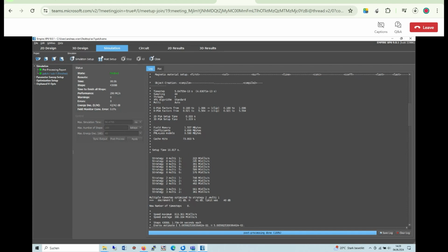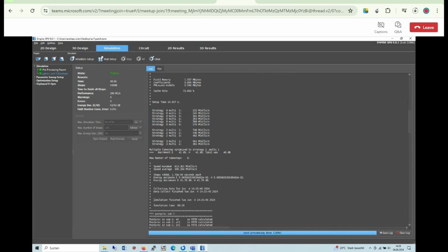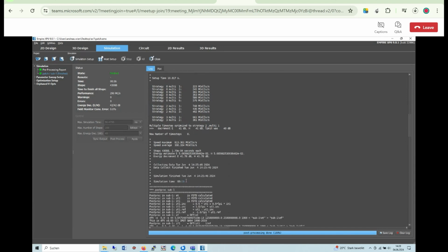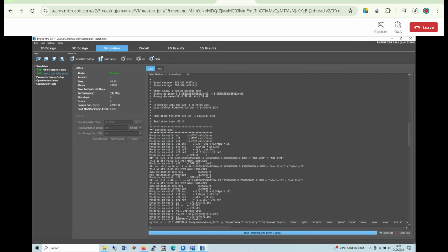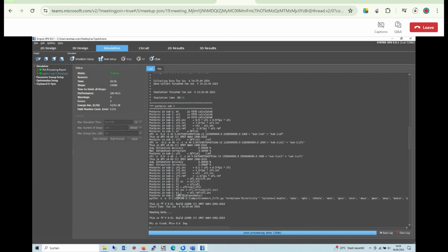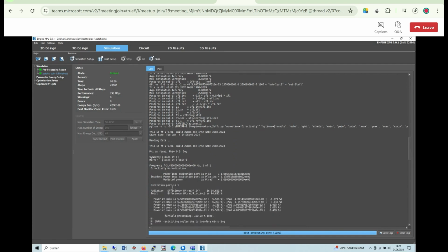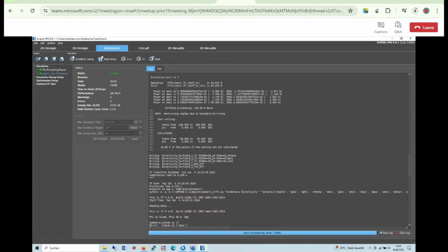And in the first steps, it tries to optimize the speed. So there's an automatic adjustment of the best strategy for the multiple time stepping. And then the simulation finished, after about 18 seconds. And then the post-processing starts, with a typical calculation of DFT and incident and reflected waves as parameters, and then there is a far field calculation going on.